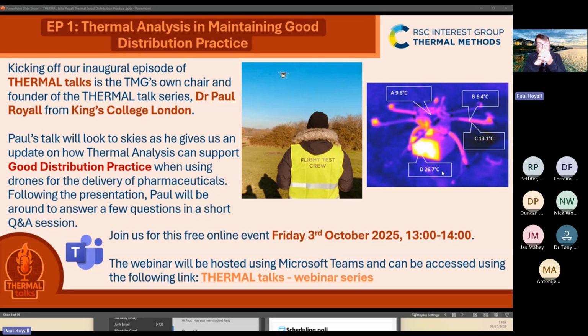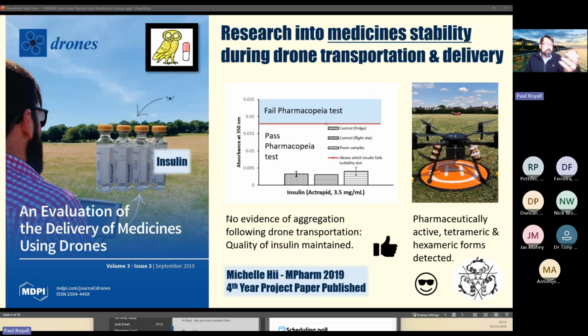And so the impact was, move your box relative to the sun during a trip, paint your box with shiny material to deflect the sunlight rather than absorb it. Because if we look here, I've got different temperatures. I've got 6 on one side and 26 on the other. So I've got a 20-degree temperature difference because it's a really cold day. Then I'm going to get airflow inside the box. I'm going to get gradients that could cause us all sorts of problems. So that's application of thermal analysis directly on the day of doing a flight.